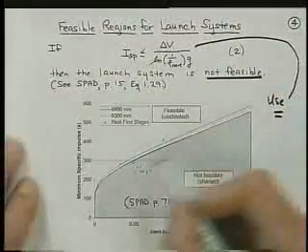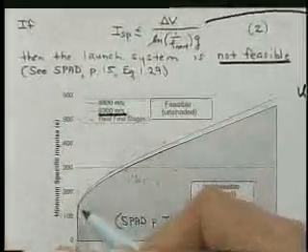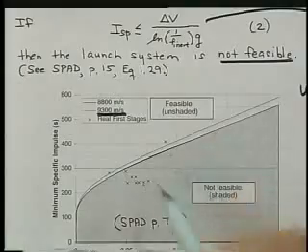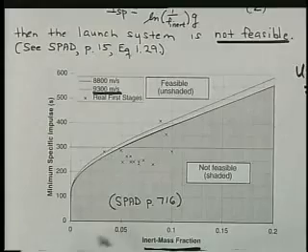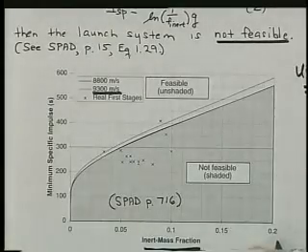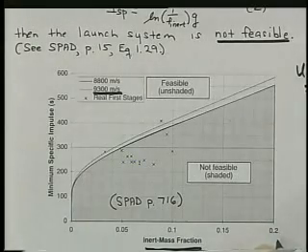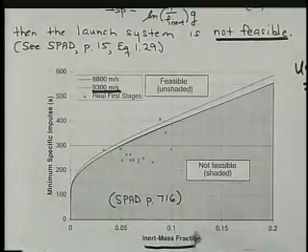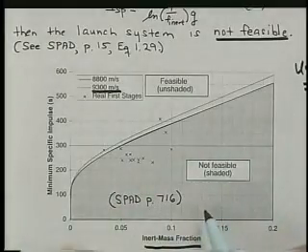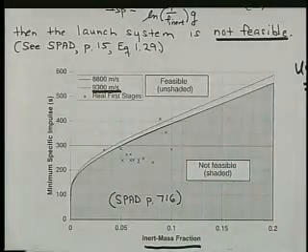from this equation, and if we put in, say, 9,300 meters per second, then we get this curve here. And that's a curve as a function of inert mass fraction. Okay, we're running that value from 0 to 0.2. So here's where 20% of your vehicle is structure, which is a very high percentage to devote to the materials that are not providing payload and they're not propellant. So everything in this gray area and actually below this upper curve would be not feasible.